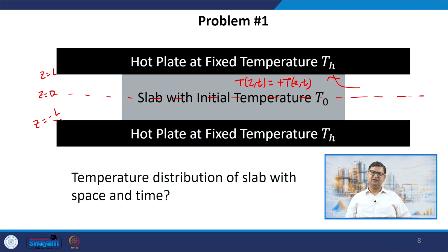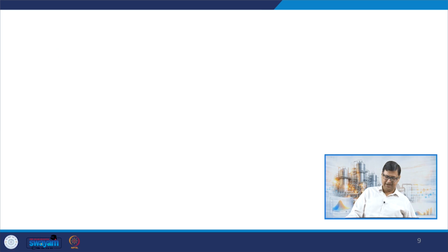And I can again do the 1D approximation, because I can imagine again that the thickness of the slab is much less than the length and the width of the slab. For any slab we can say that, because the meaning of a slab is typically that the thickness is much less than the length and width anyway. So I can make those two approximations, but now the other boundary condition is going to change. Let me draw this now.